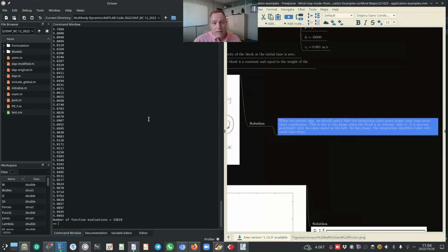When will we then use a large or a coarse reporting time step? That is for animation purposes, if you want your animation to run quickly. Remember I said in an earlier lecture that the animation is really a sanity check to see whether the simulation performed as we expected.